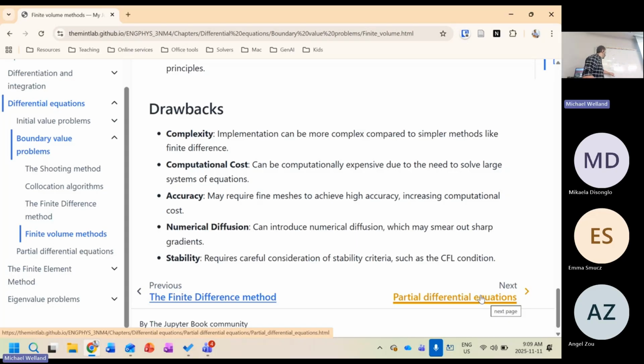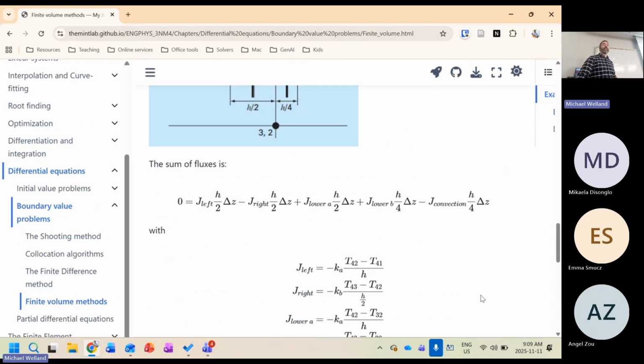In putting in this boundary condition, you have put on a constraint. You've added an equation onto this relationship between T1 and T0. So you forced that gradient to be 10. Okay? With finite volume, you don't actually do that.